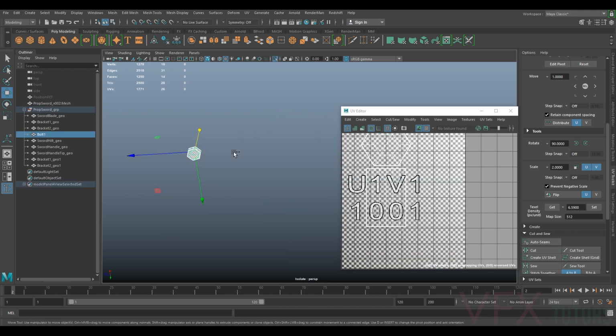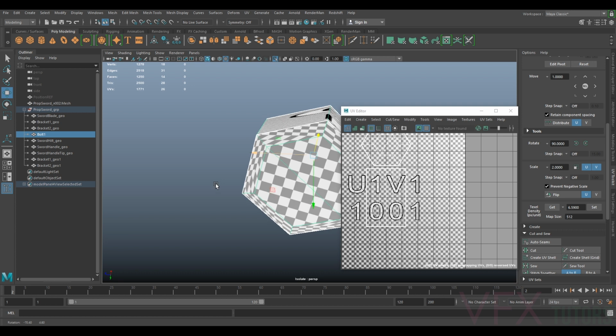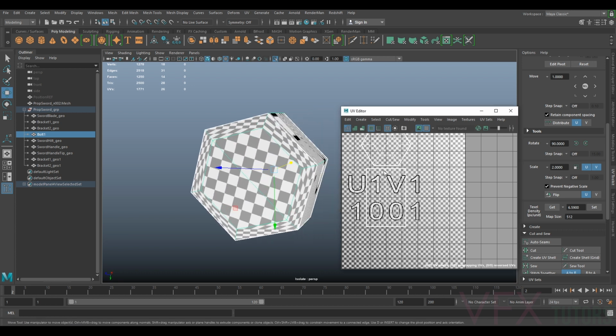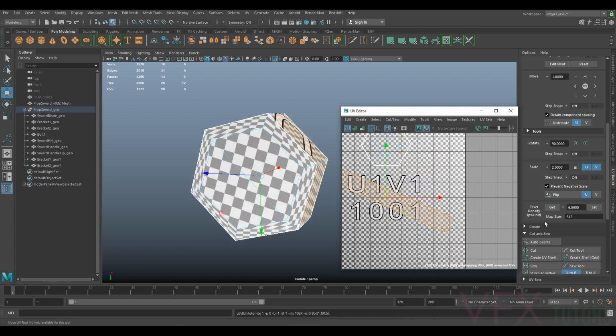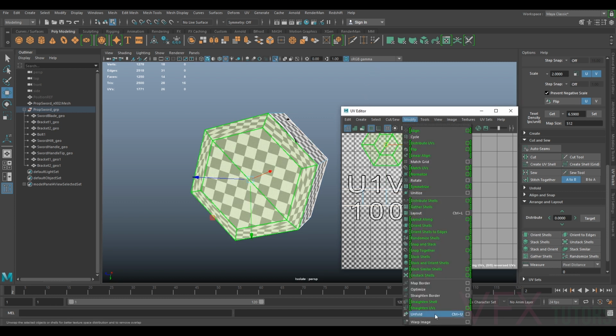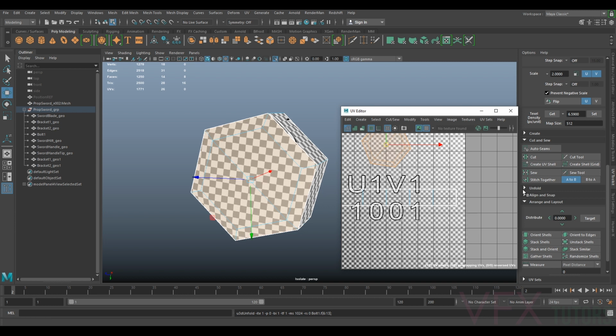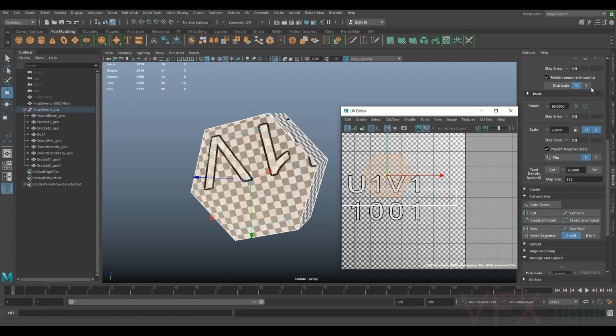So these should be fairly easy, because they're actually partially already done for us. So we can just go to UV shell, modify, unfold, orientate shell, and the same with this, modify, unfold, and then we can just double check it's the right way up.